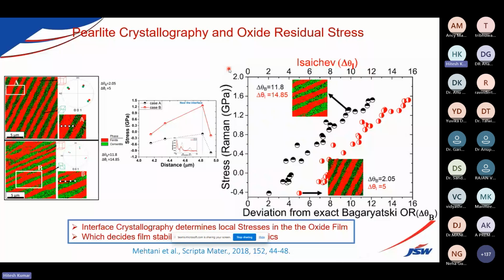So if you can see, these lamellas are around 7 to 8, around 1 micron. There is 1 micron difference between one ferrite and another, one cementite and another cementite. So this is called coarse pearlitic colonies. Okay, so then we did the EBSD to find out the phase fractions of the pearlite.